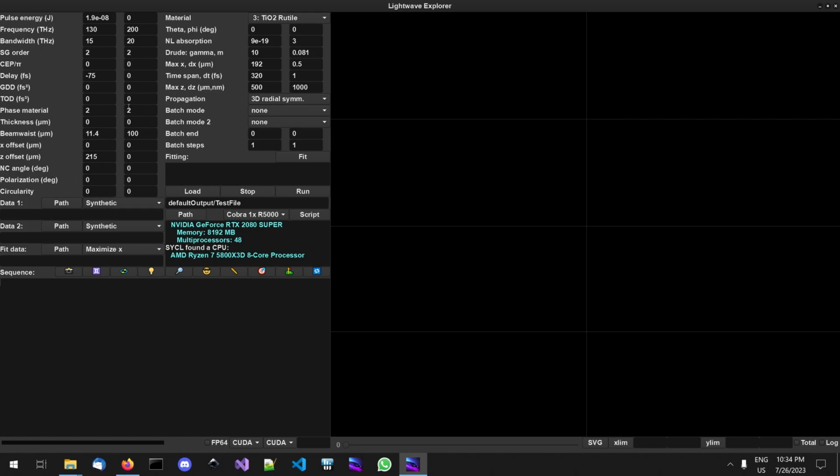If you look on the left-hand side, there are 2 columns of numbers, quite a lot of numbers. These are all parameters describing an ultrafast laser pulse. By default, you can interact 2 of them inside of your nonlinear medium, and we have some ways to introduce more if you need them. But to start with, we're going to look at some simulations that just need 1 or 2 pulses. The default values in here are typical pulse parameters for a chromium zinc sulfide laser. There are quite a lot of them.